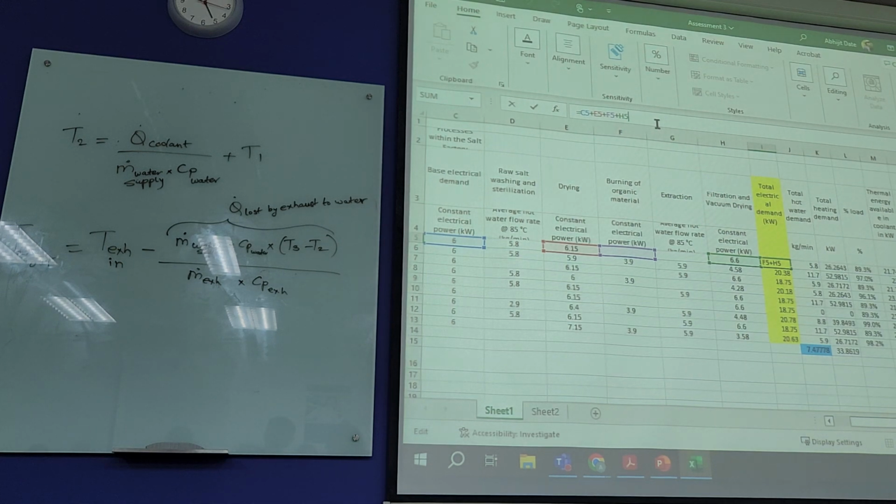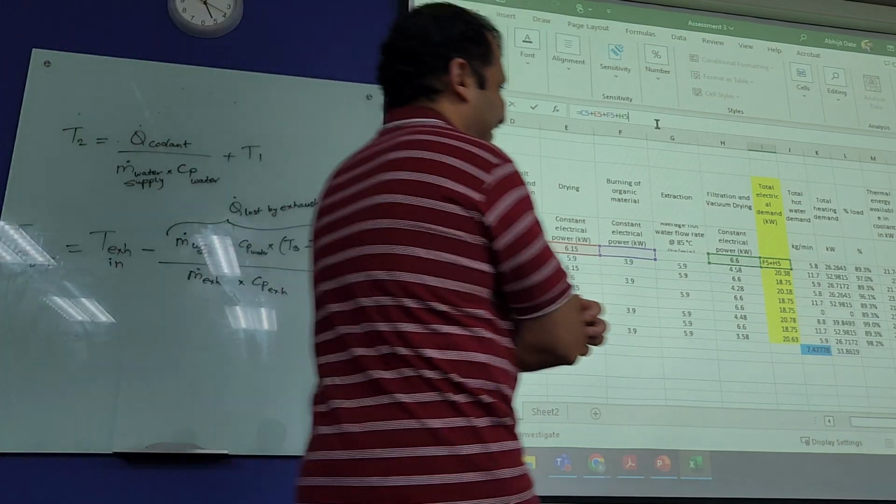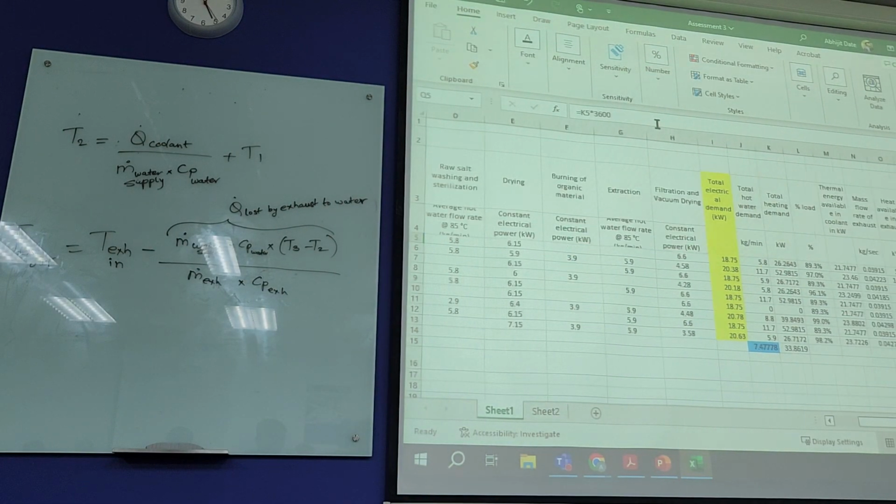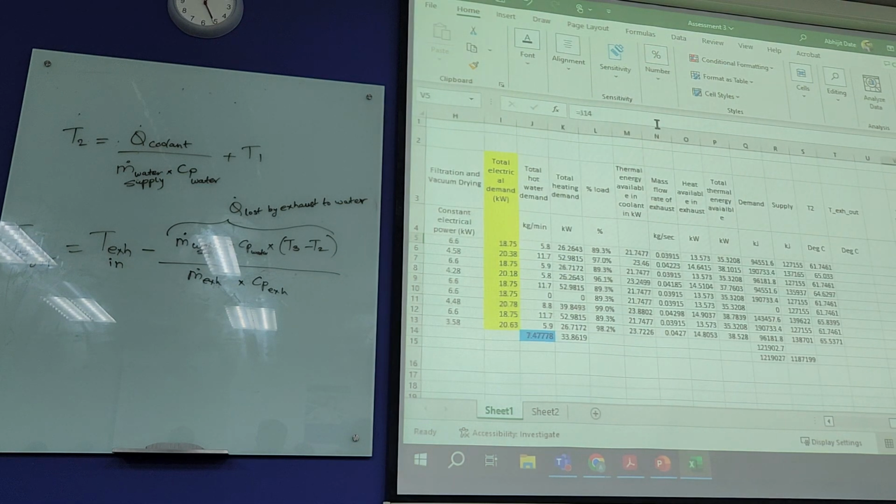The 977 is the density. So you get this one, the volume flow rate. But then this one is in kg per day, so if you change day to hours, it's 24 hours. Someone asking me a question. Because 1 kg is 1 liter, at least at 20 degrees Celsius. But the one we're supposed to find is at 85 degrees Celsius, the weight at 85 degrees Celsius.